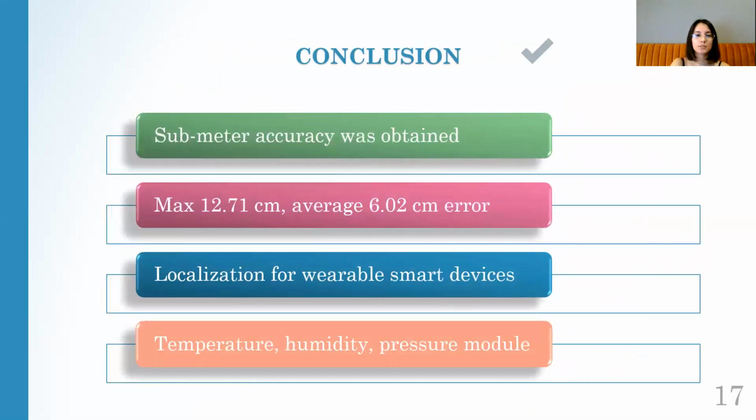In conclusion, in this study, a TDOA-based algorithm has been developed to reduce the communication traffic for real-time and high-precision localization needs and increase localization performance. With this algorithm, it's aimed to calculate the location with a 30 centimeters precision. Measurements were made with 4 different anchors and 12 different tags in the experimental setup for localization.